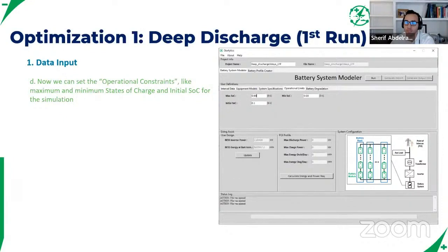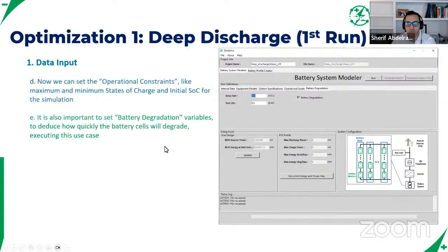So that's why in the design process, you want to account for the smaller depth of discharge that you have access to in your battery. Here, we're being a little bit optimistic with 93% and 3%. In reality, this would probably be more around 90%, and this would probably be 10% for most LFP batteries out there.